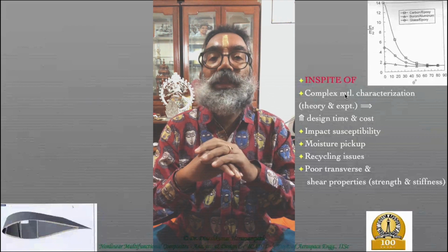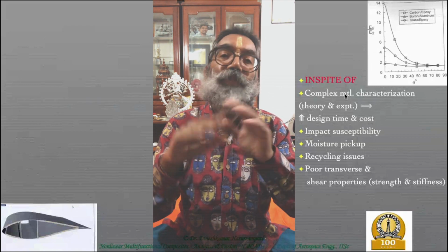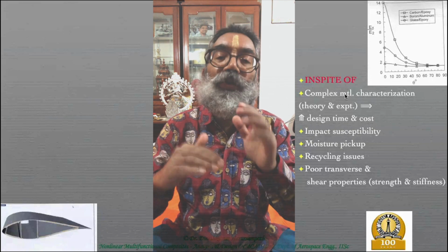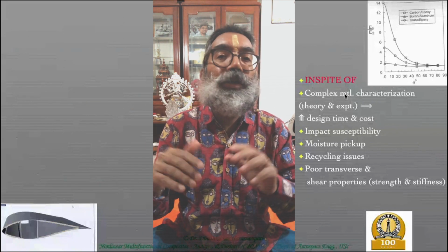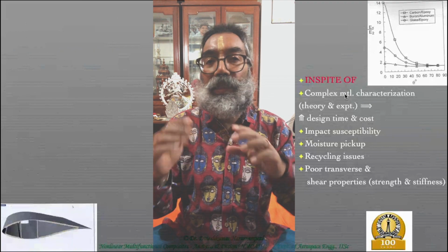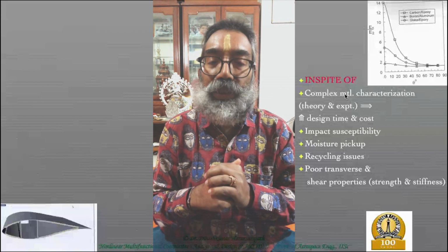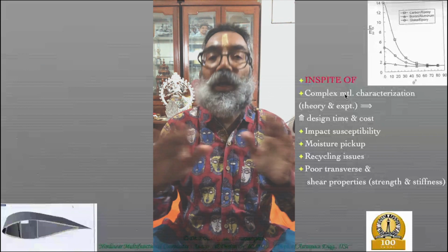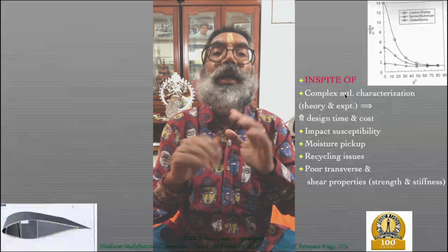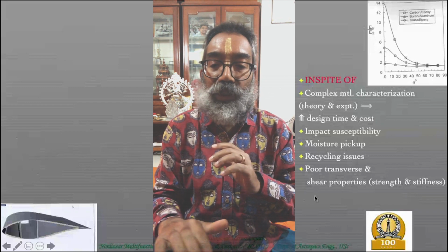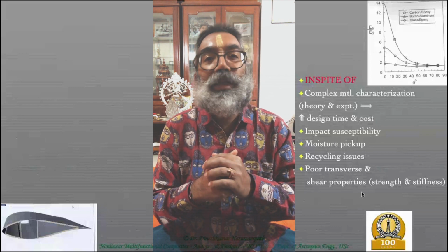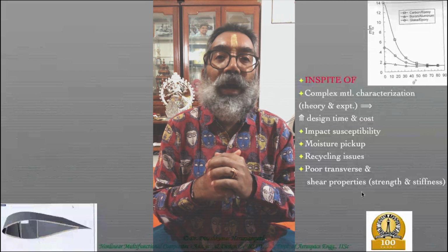A quasi-isotropic laminate which has plus minus 45 and 0/90 is the simplest design. You can go for multiple layers where you do not need 45, but can do with 30, 60, etc., as you increase the number of layers. For now, let's avoid those complications, but once you have a quasi-isotropic laminate, that takes care of this particular issue to a large extent, because now there's no such thing as a transverse direction, and shear can be handled as well.